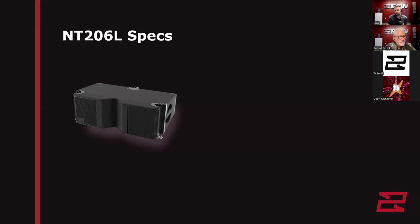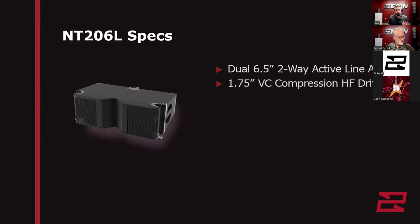So before I get into how this product operates, I want to go over some of the key specs. And Robert covered some of these, but I think these numbers are important to know and to reiterate. So this is a dual 6-inch two-way active line array system. It has a 1.75-inch voice coil compression high frequency driver. It's all powered by 1500 watts of amplification.